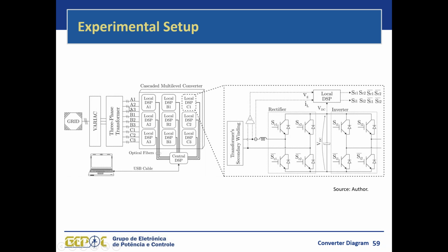Each phase has 3 secondaries, but they are standard secondaries. They don't have any different windings or different angles. So all these issues regarding the rectification are dealt with by the control of the rectifier. So we have low distortion input currents because of the active rectification and of the simple three-phase transformer here.